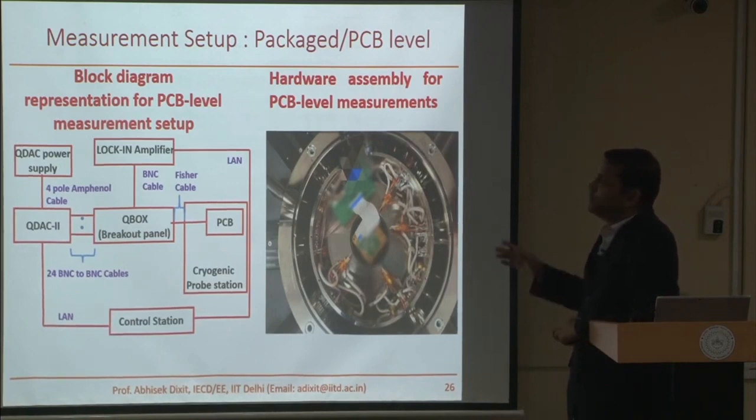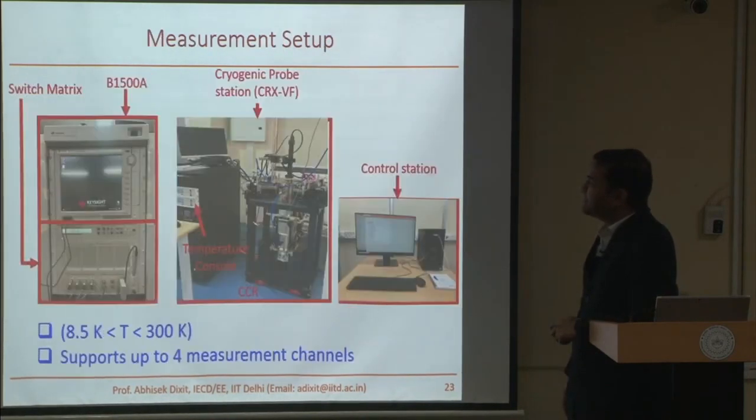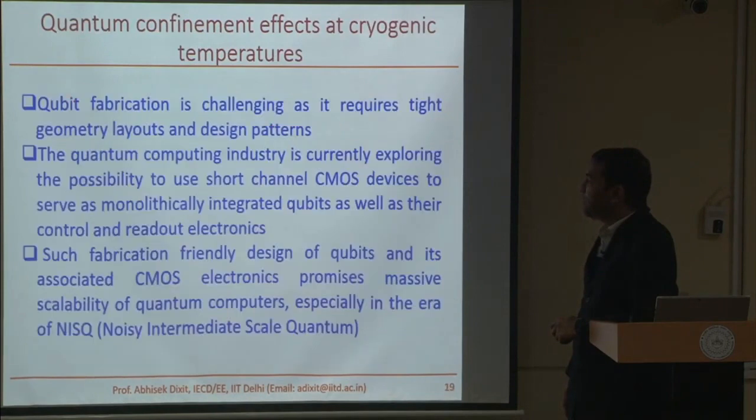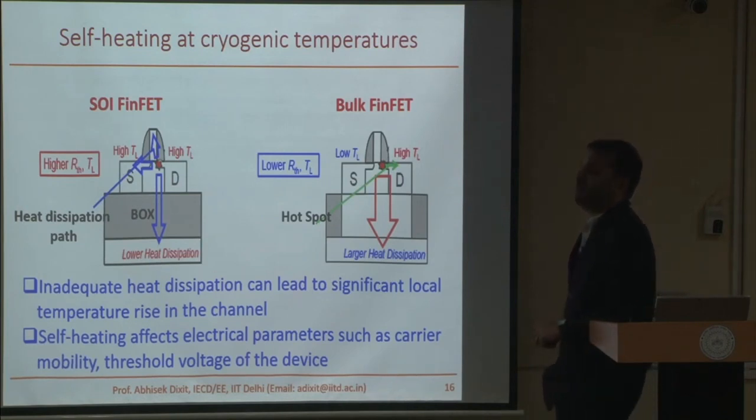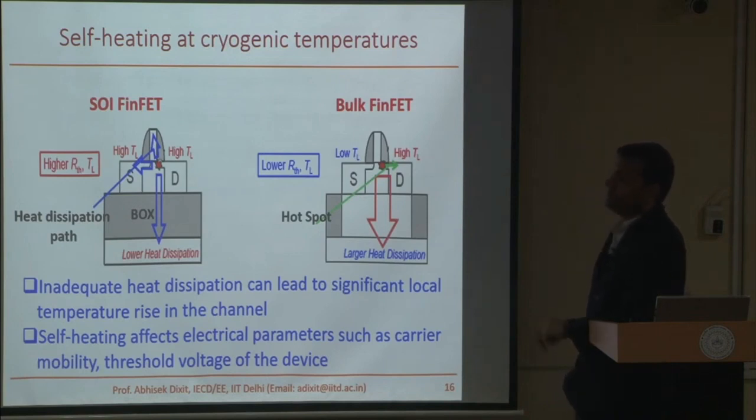If you really want to know the junction temperature, then you have no other option but to fall back to that self-heating kind of analysis, heater and sensor and all that. We just got devices from one of the vendors, where they have all this heater, sensor, gate resistance, all kinds of layout, but we have not been able to put it to measurement yet. But we'll do that. Maybe within the next 2 to 3 months we'll have done that.